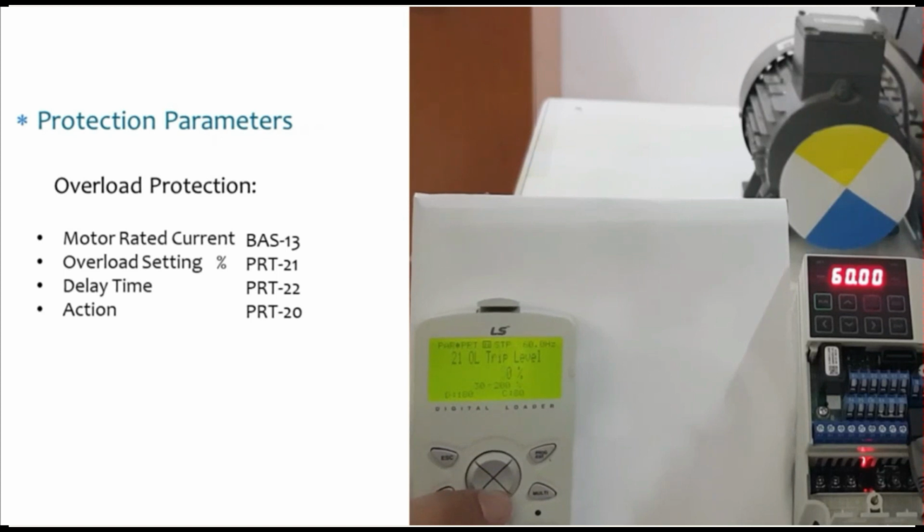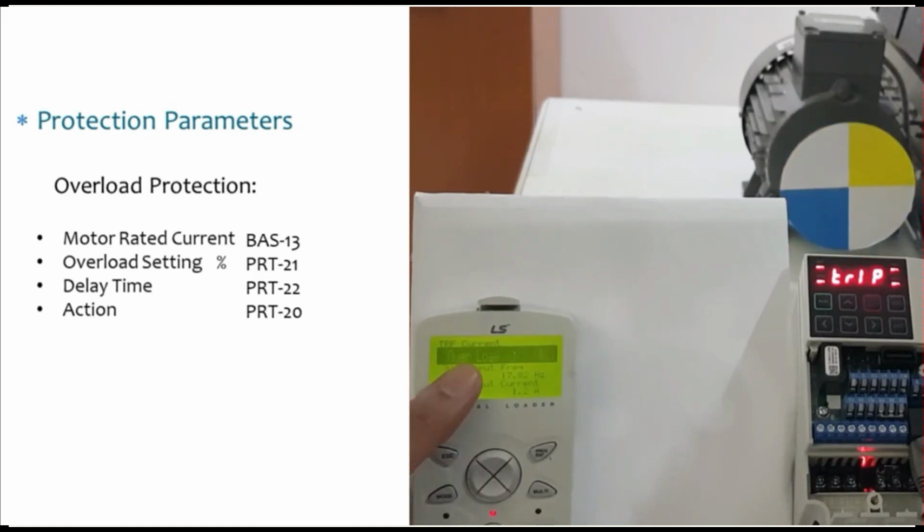As you can see in the demo, we deliberately put the overload trip at 50% for the purpose of simulation and trip delay time at 5 seconds. The motor rated current is 1.8 amps. And the action we select is deceleration. Let's start the motor. So 5 seconds pass and overload trip showed up.